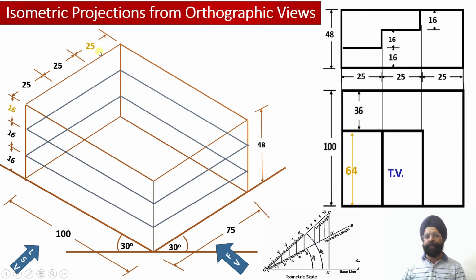So these 3 steps I have appropriately located onto the top face, and corresponding to step 1 we are going to draw a horizontal line, and corresponding to this width of 36 millimeter, we are going to draw another projection line over here, so that once I have drawn both of these projection lines, this L-shaped surface has been obtained over here.